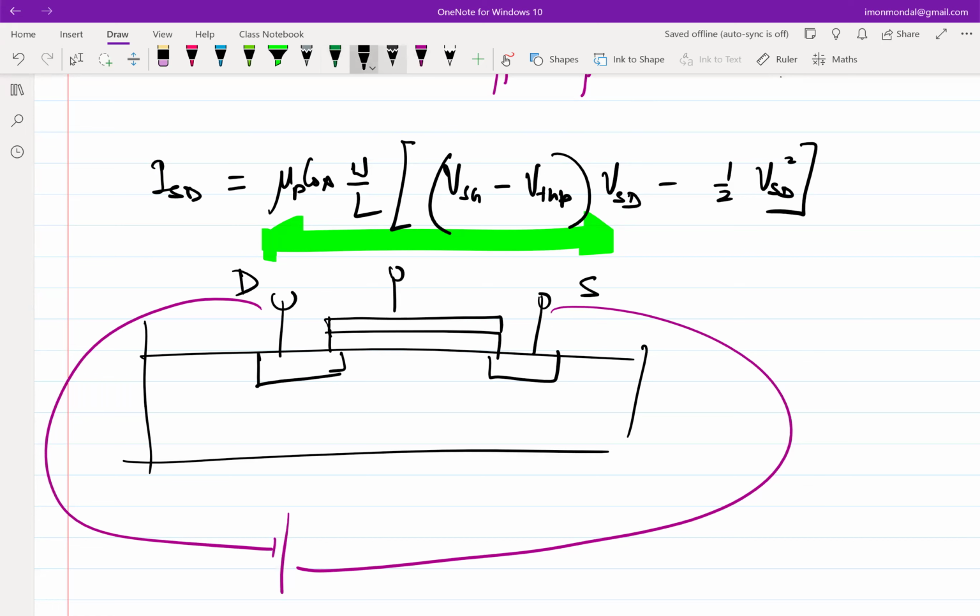and assuming that there is a battery that has been connected between the gate and the source, which has given rise to mobile charges here, and the concentration of mobile charges under the assumption that the drain and source are at the same voltage will have a profile of a rectangular slab, right? Because there is no way you can identify which side is source, which side is drain, because geometrically also they are the same, electrically this device is identical.